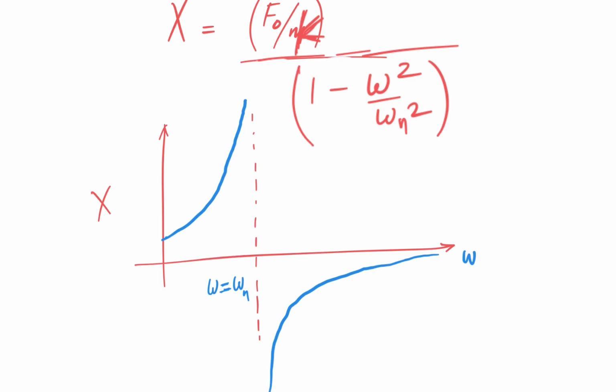So you can see here at resonance the value peaks up like this, and away from resonance the response comes down, and it starts with 1 when you have omega equal to 0, where omega is your excitation frequency and omega n is your natural frequency. And here also you can clearly see a shift in the phase angle. Shift in the phase angle is quite evident here as well.